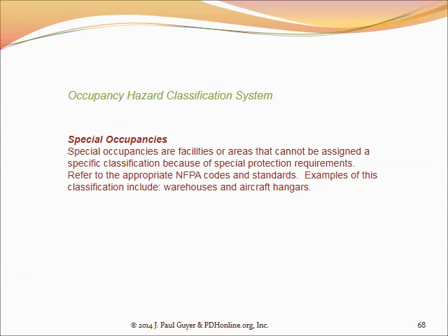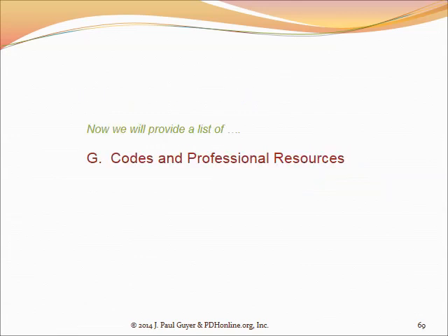Warehouses, because of typically the large amount of fuel that is stored, and that means burnable materials that are in typical warehouses. And there are codes, NFPA codes, that address these special occupancies. These next few slides are just a listing of the many codes that are produced by NFPA and to a much lesser extent by the International Code Council and one or two other organizations that are relevant in the fire protection area.